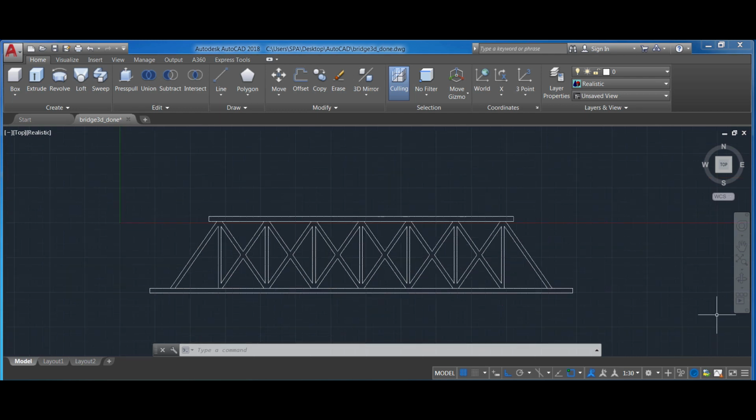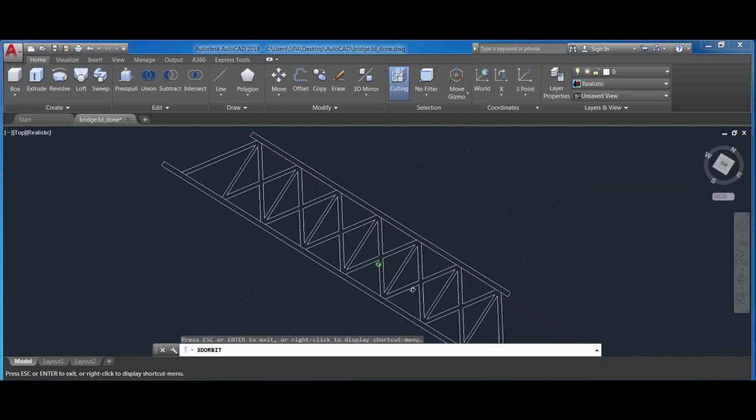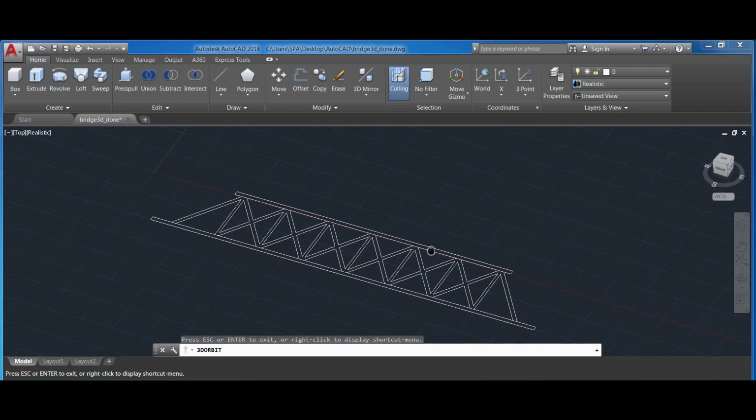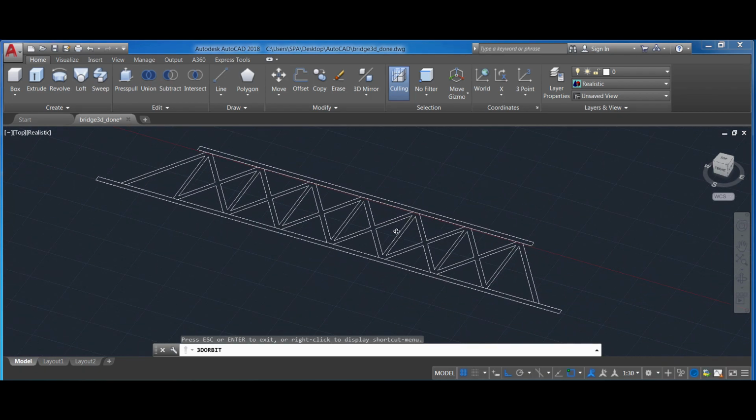So what I'm gonna do is go back here and orbit it, slant it a little bit, because it's always good to have this kind of semi-isometric view or slanted view when you extrude something. And now I'm ready to go ahead and extrude. But actually extruding is not gonna work for the same reason that it didn't work before. So what I'm gonna need to do is use the press pull command.